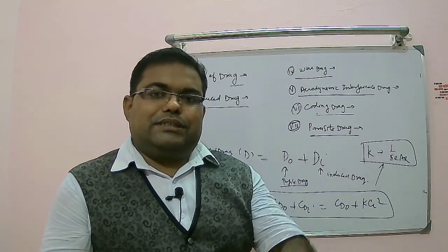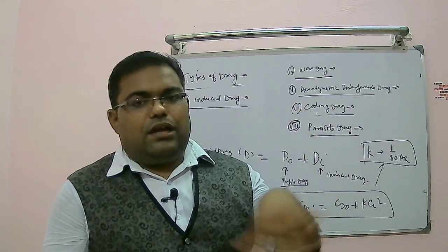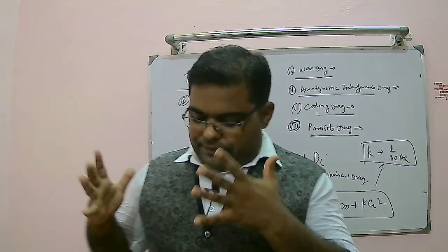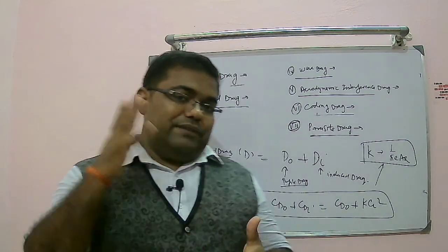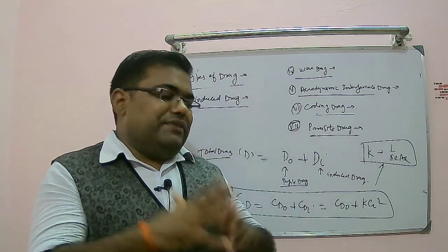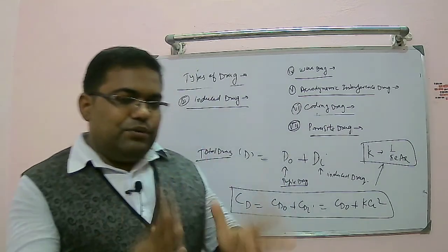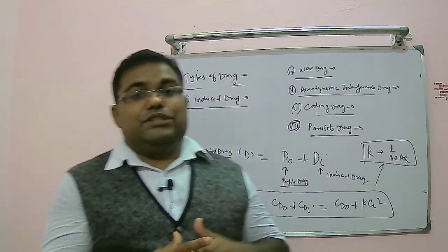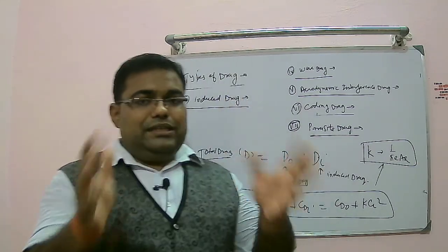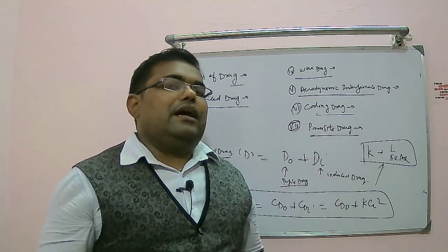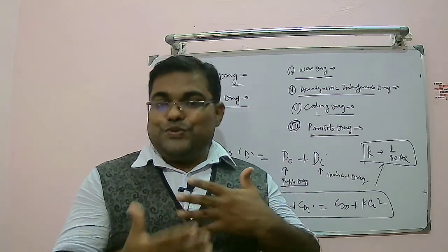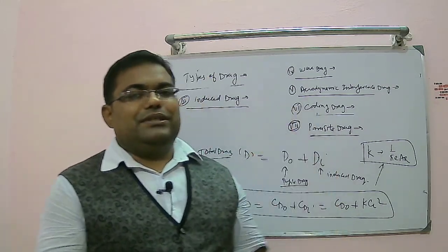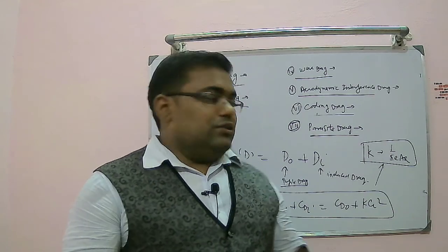So today we have discussed pressure distribution. We have seen how important pressure distribution is, right, to find the aerodynamic forces, and we have developed a relationship for lift and drag, and we have seen examples of lift and drag over different kinds of geometries, right? Finally we come to the conclusion that streamlining of objects is much necessary for vehicles traveling through the air. That's why all the parts which are exposed to the outer atmosphere are usually curved in the aircraft. Why am I making them curved? We don't want any sharp corners. Sharp corners contribute a large amount of drag. That is called streamlining.